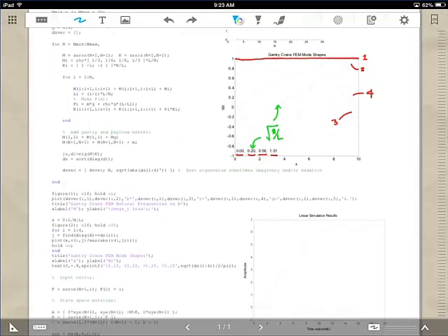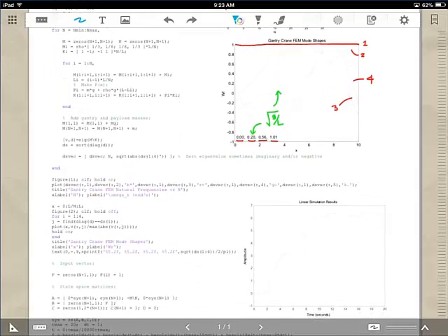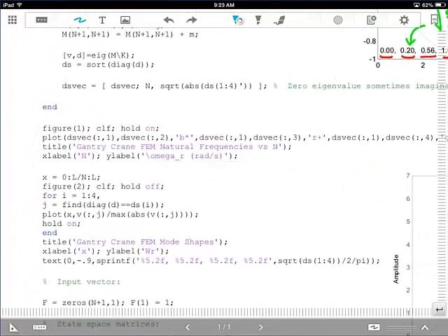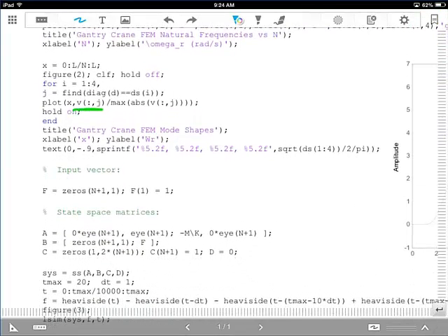So by describing the mode shapes, I'm basically doing the same thing we did before by looking at the eigenvectors and plotting them up. In this case, you don't need to worry about adding zeros to the 2n because we're solving for all of the nodes in this problem. Just plotting out here the frequencies that you get.